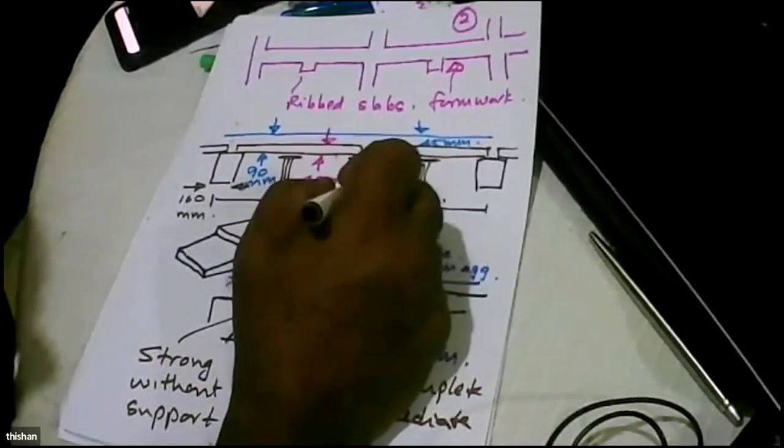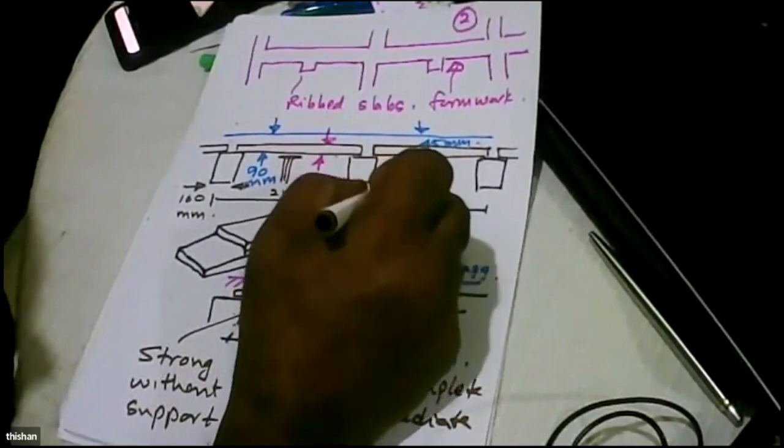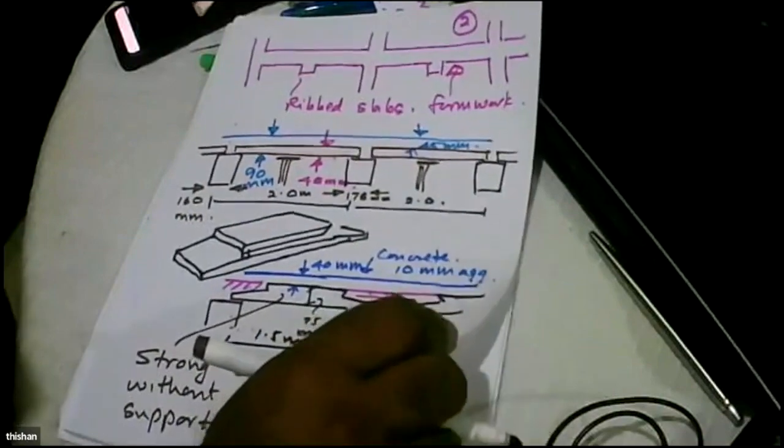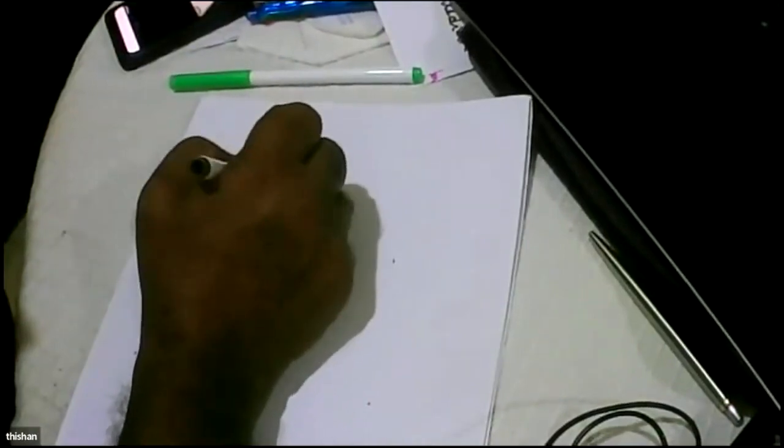Then we looked at the constructability. We thought, if you are going to cast this beam in situ, or we precast it, but we have some lifting equipment like a crane or a tower crane to lift the beam, then the weight of the beam is not a major problem. So we thought, okay, let's do this. Considering that the beam will be cast in situ, we selected a width of 175.